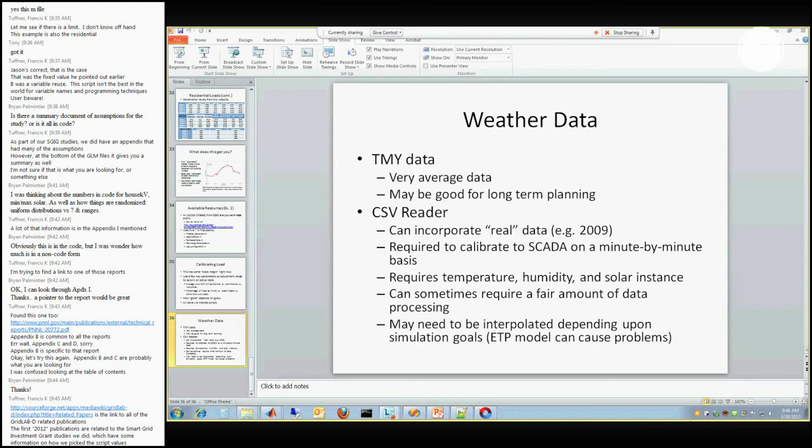And I think they have data all the way back to about 2006, 2007, and they display it in an HTML format that's pretty easy to parse and things like that. But again, that information needs to be timestamp matched with your SCADA substation data, or whatever you're using to calibrate your load to. Because if you don't, then you're going to get some serious differences.